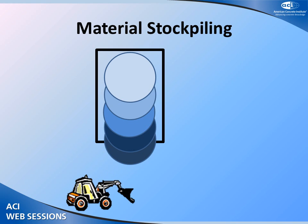Looking at material stockpiling. What happens all too often is we've got a bin right here, or a bin set out on the ground. We add our first load of sand, then we add another load of sand in front of that, and more loads of sand. Well, the sand that usually comes in is going to be the wettest. So here we have had sand that's had time to dry out. And so what's happening is our front end loader comes here, grabs sand, gradually works its way back, is getting into drier and drier material, which is going to impact the moisture content in the sand.